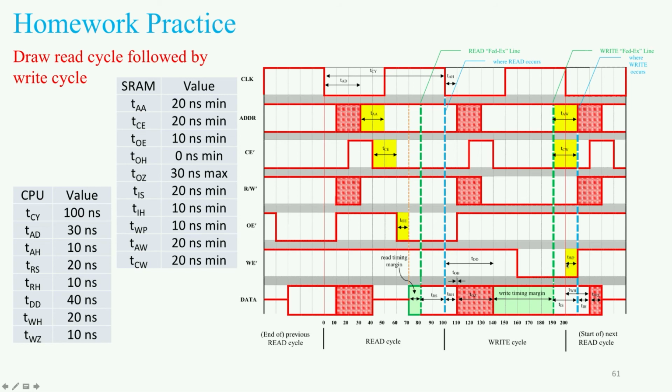And say that, okay, the SRAM, this is satisfied, there's no problem here with setting up the SRAM. It's definitely valid for at least this much time. Now we take a look at TCW. Is the chip enable bit valid for at least this much time, 20 nanoseconds in this case? And it turns out that it is. Okay, it was valid right here.